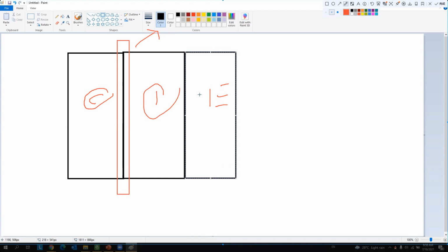So from a very fundamental concept, we need to understand how terrace houses are actually built structurally. Then we are able to break it down, determine the shared portion, and make the amendment on the quantity. If not, say this brick wall is 10 meter cube, and in your BQ you put 10 meter cube for the corner lot and also 10 meter cube for the intermediate, the quantity will be excessive, which is not what we want.